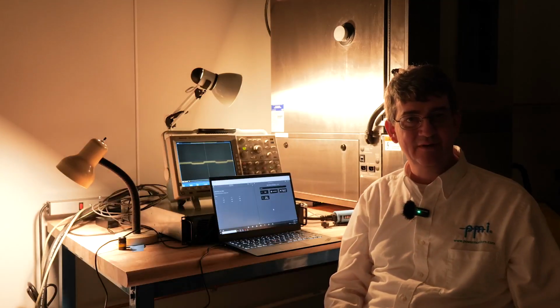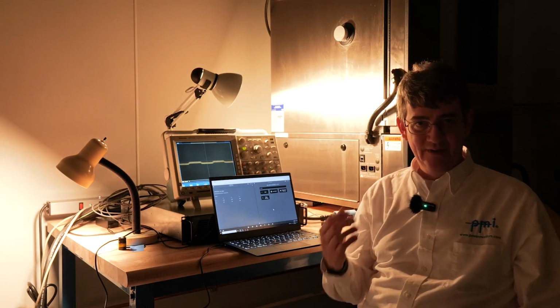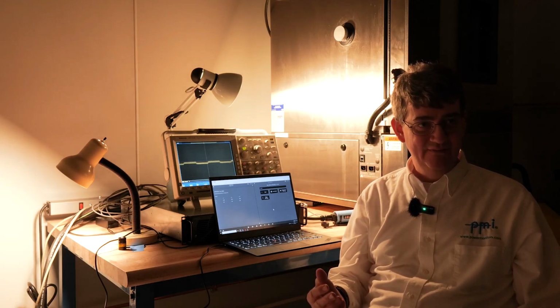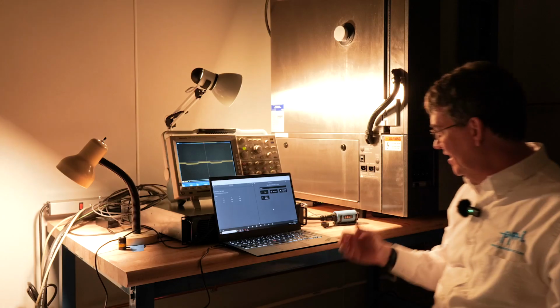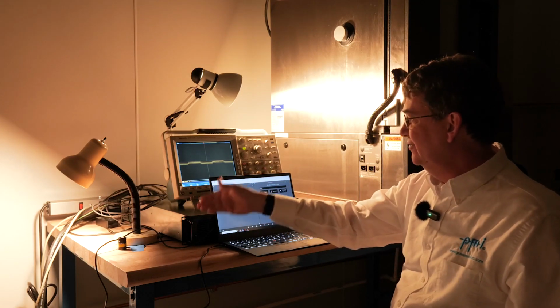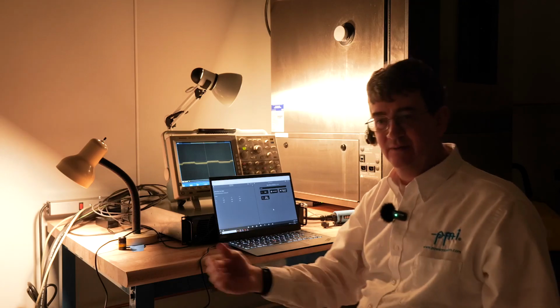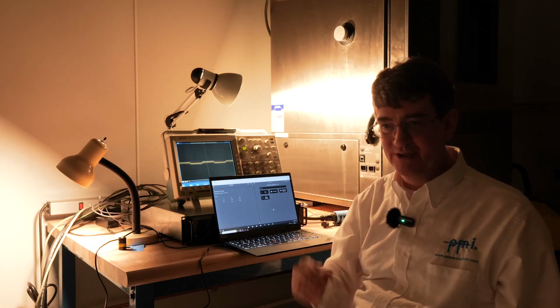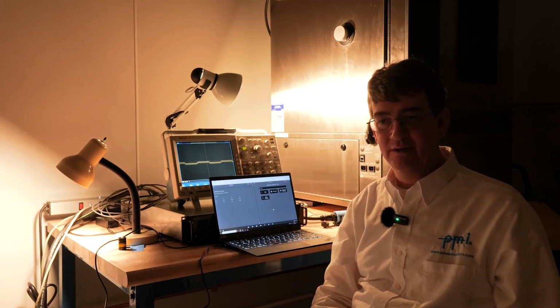Today we're measuring the flicker measurement capability of the Bolt. The flicker standard that we're using is IEEE 1453, and in our test setup we have a Bolt that is connected to an AC power supply, and we can program this power supply with arbitrary levels of voltage variation that should generate known flicker metrics.